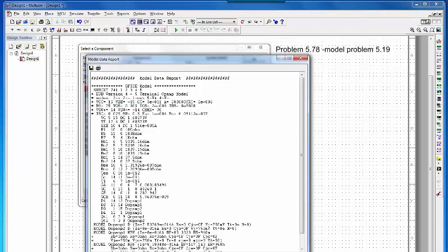It also says my input resistance is 2 mega ohms right here. This is the input resistance. It says 2e to the plus 6. So input resistance is 2 mega ohms. Looks like output resistance is 75 ohms. The open circuit VOS, V open circuit, is 0.001 volts. I short circuit is a very small current.